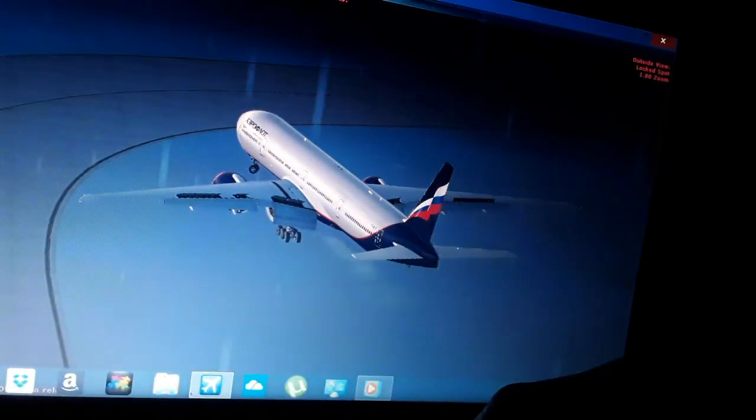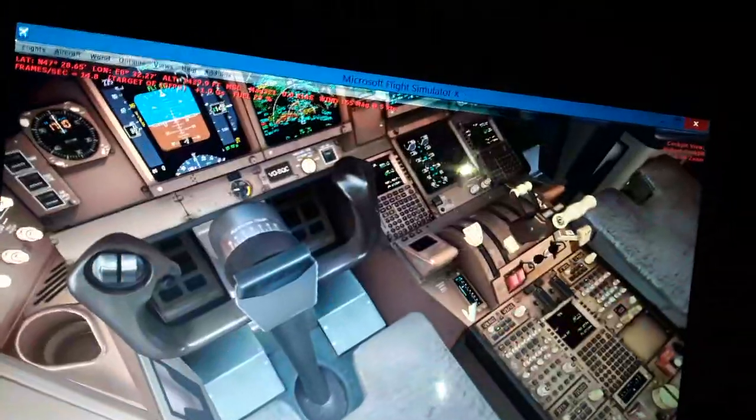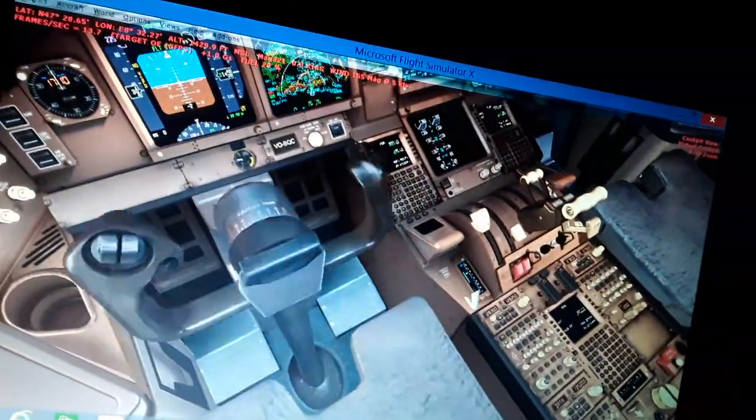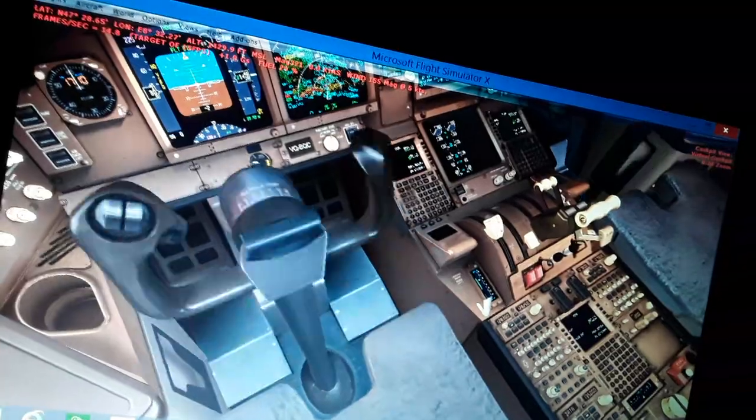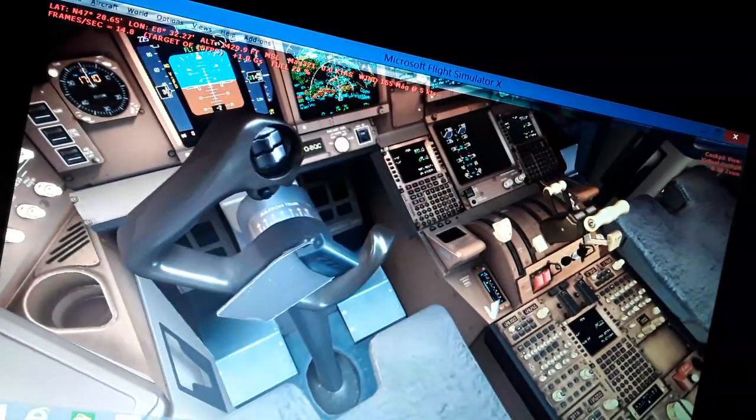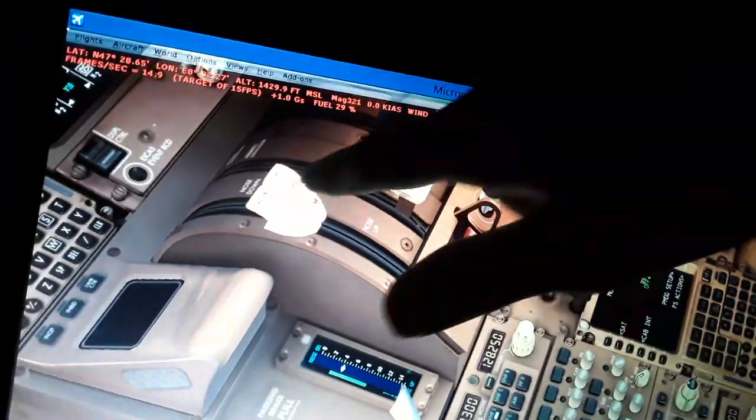So this is for the outside view of the aircraft and the flight control. We have a little bit more. So you can see also the control column and control wheel, the elevator pitch up and pitch down, the ailerons and spoilers, the stabilizer trims here and here, the horizontal tail of the aircraft. You can see the position in degrees, 4 degrees up, and we have the normal and the alternate pitch trim. You can use either this or leave it to the auto.